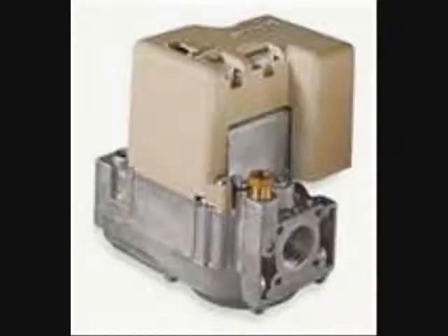Your main burner is now turned on. This is achieved by sending 24 volts to the MV terminal on the gas valve. This could be varied by having a smart valve. These valves have pin connectors and are hard to diagnose.